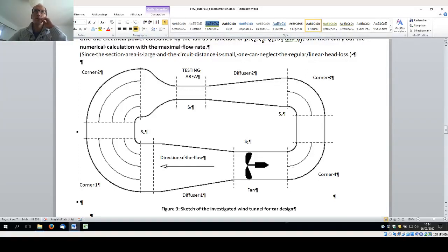So here you need to think about a property of the flow problem that you study in this condition, which is that it is a closed loop. The flow is getting here, and after getting out it is getting again here. So it's turning on itself. So what is possible in such a condition is to take the whole wind tunnel, the complete loop, as the control volume.